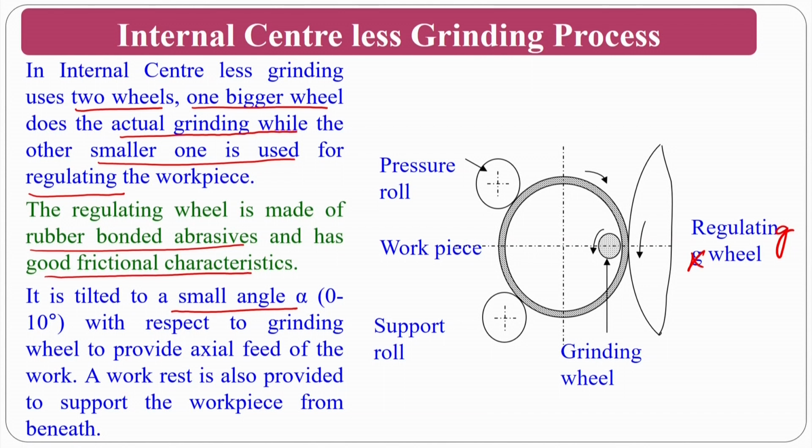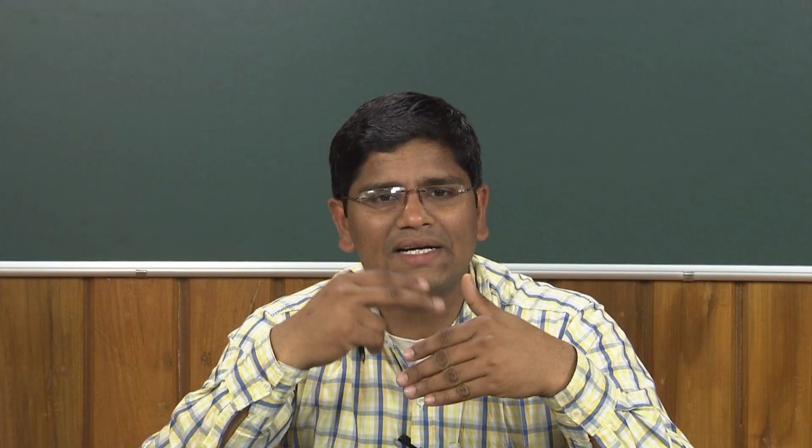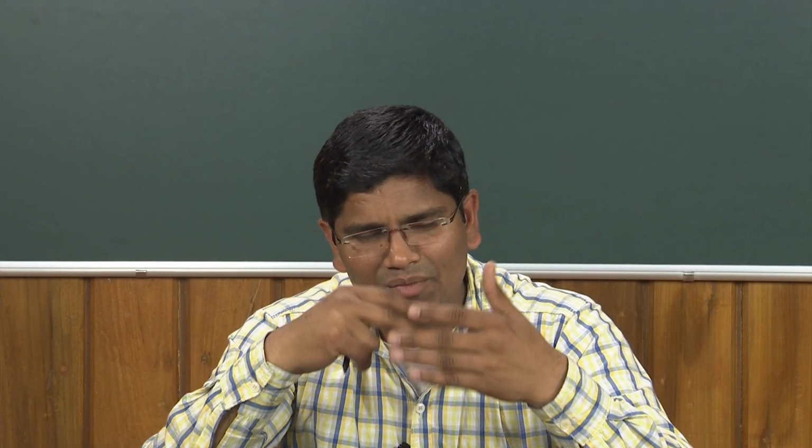So what I mean to say is that if I have irregular shapes like cams, for example, that I want to grind, normally you will go for the external centerless grinding process. Similarly, if you have hollow things, you can go for the internal centerless grinding process.